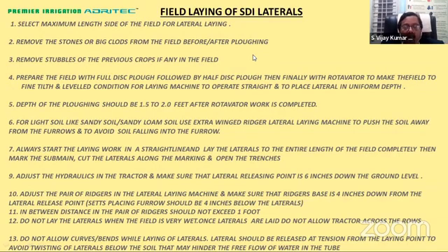Do not lay the laterals when the field is very wet, because the tractor is going to totally disturb the whole thing. Also, once the field is laid out, do not allow the tractor to go in the opposite direction across the rows.